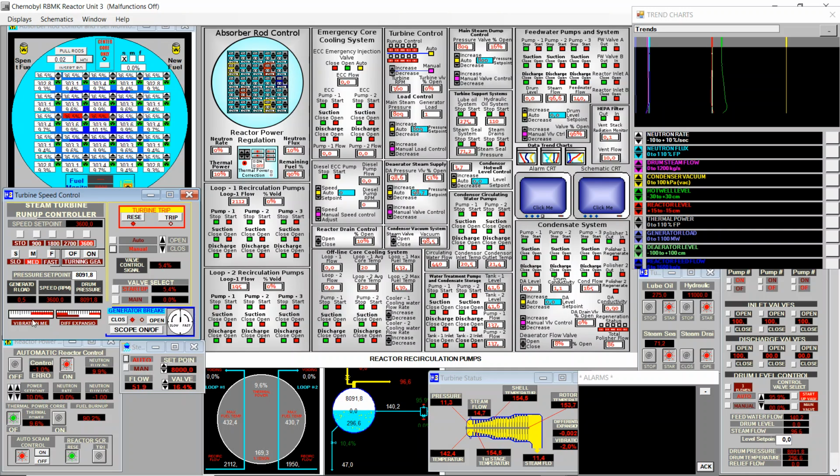So this is the power that will spin up the turbine now when I open the brake. I will open the brake now, and immediately I will close a bit more the valve. So I open it, and you see the speed going to 3604.05. So I need to decrease a tad more. Let's decrease it to 3.9.